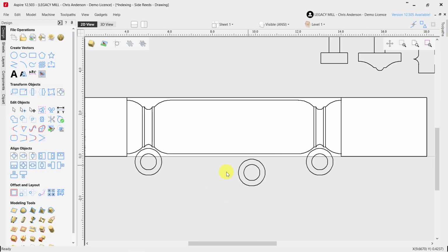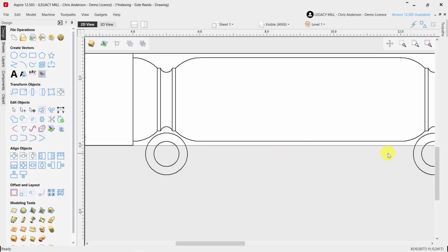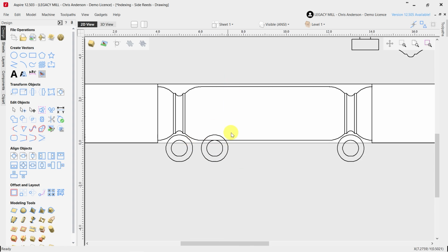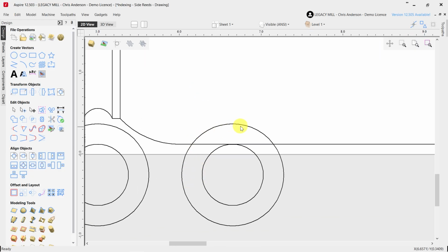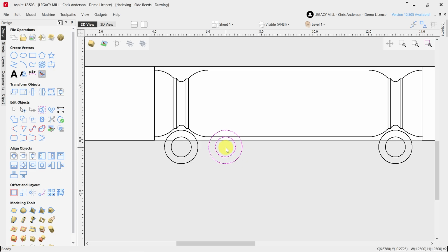And so if we're looking at this now as a perspective from a top view, where the cutter is going to be rotating, we can visualize where we want the cuts to start and end. Now, what the software is going to do in Cam Pro automatically is take the inner radius of the carbide and apply it up against the section diameter that we're going to be stating. And we're going to answer that here in just a moment. So it's going to apply all of that cut as the cutter is swinging through the material on the edge of the part. And again, that's just going to travel all the way down the length until it gets to an ending point.